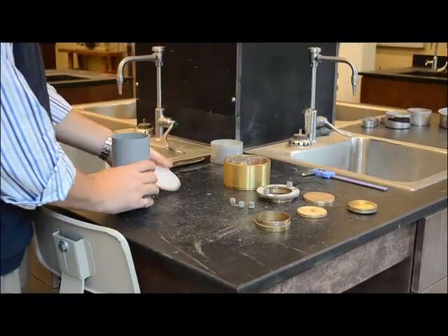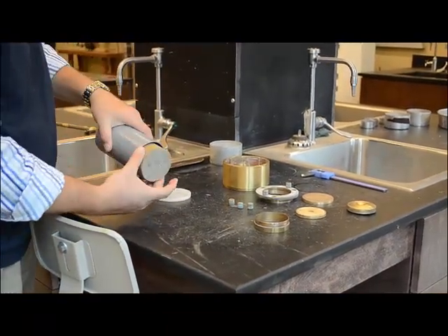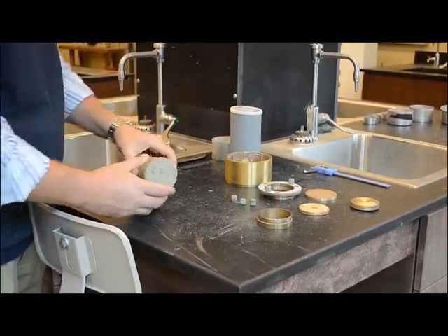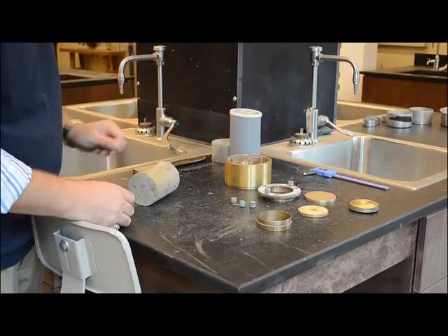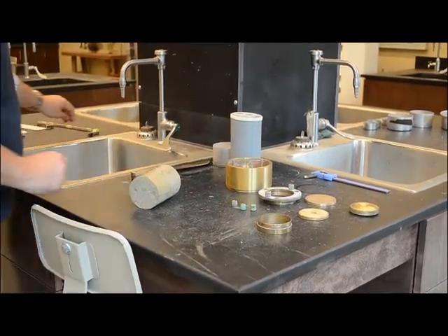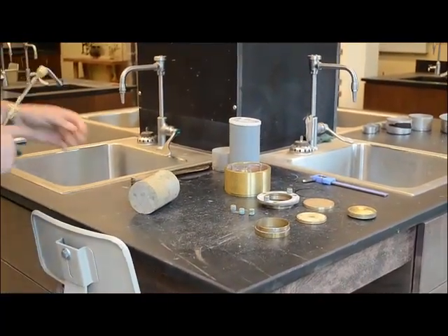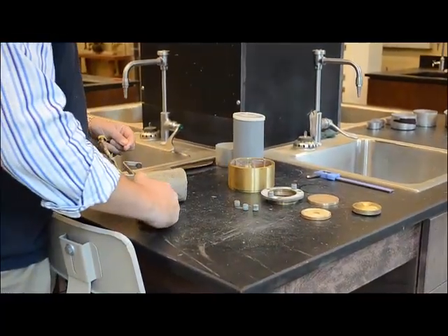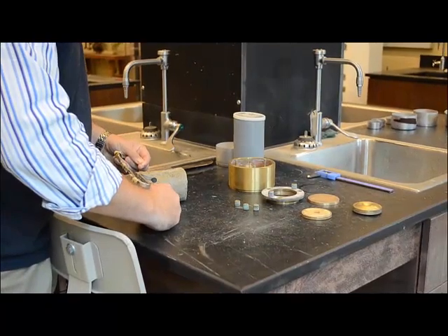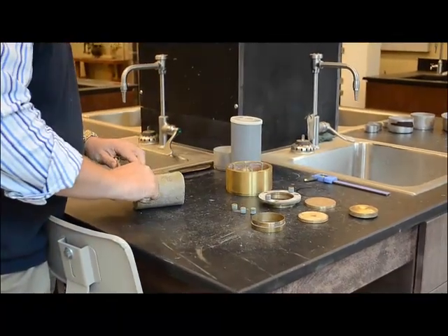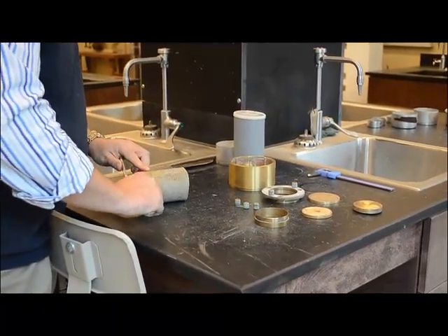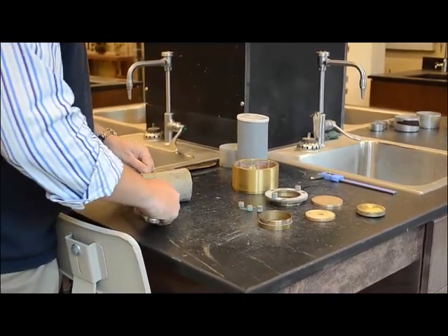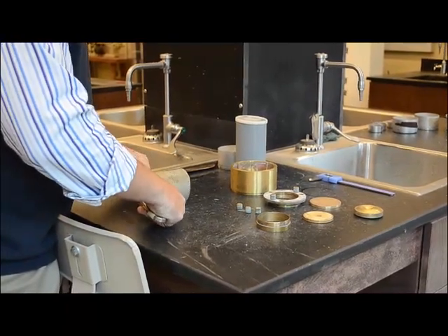Next, we'll get a soil sample. We are lucky enough to have some great companies locally to provide us with some great samples. This is a silty clay sample that was given to me for this experiment. We have a wire saw that we can cut a portion of this sample off to utilize for testing. We need to have it at least a little bit thicker than what that cutting ring is, so we can trim both the top and bottom and fill up the entire volume of that cutting ring appropriately with the soil that we need. And that's what I'm doing here now using a wire saw.